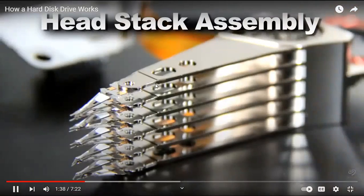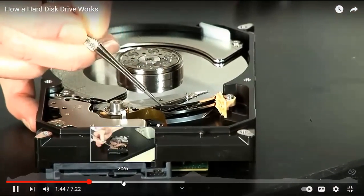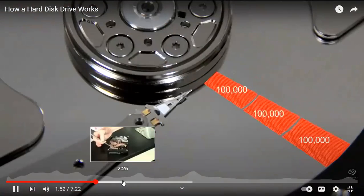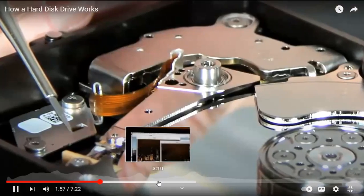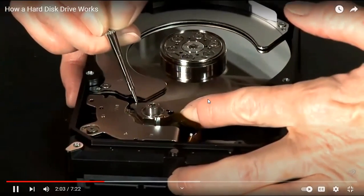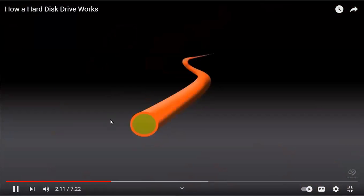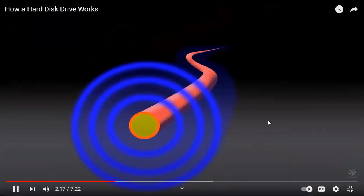This arm is part of what we call the head stack assembly. The arms move back and forth across the stroke and read the various tracks that are laid out on the disc. These tracks are so narrow that we fit about 300,000 of them in an inch of radius. The arms, the HSA pivot, is actuated in this case, and I think this is kind of fun, magnetically. As we know, electricity and magnetism exist together, and when a current is run through a wire, there is a corresponding orthogonal magnetic field.